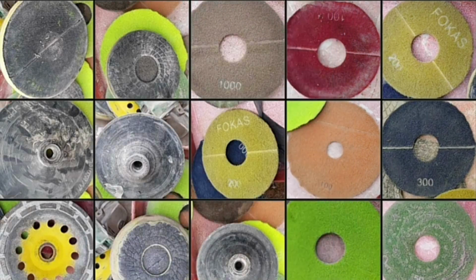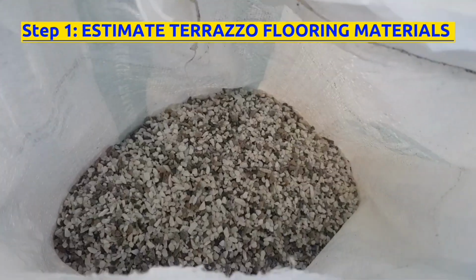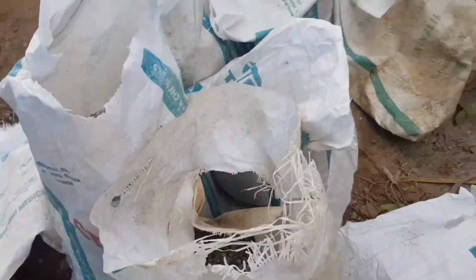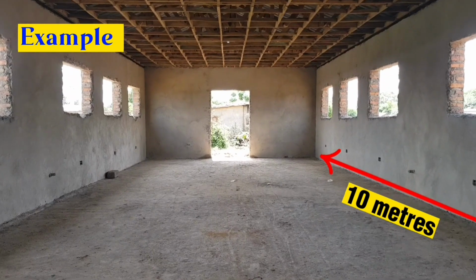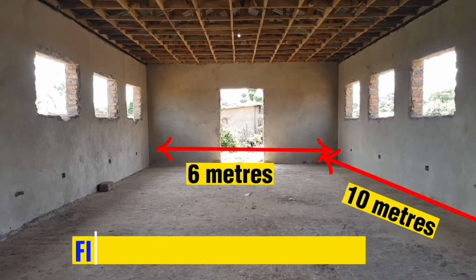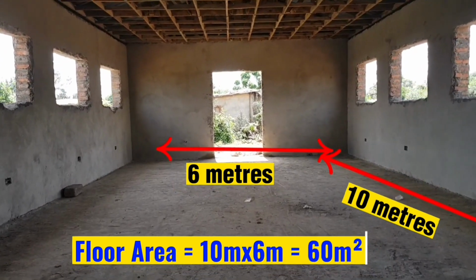Let's dive into these 10 easy steps for terrazzo flooring. The first step is to estimate the terrazzo flooring materials required for your floor, and we determine this by simply calculating the area of the floor. So for example, if the floor is 10 meters along this length and 6 meters along the width, the area of this floor is therefore 10 multiplied by 6, which gives us 60 meters squared.